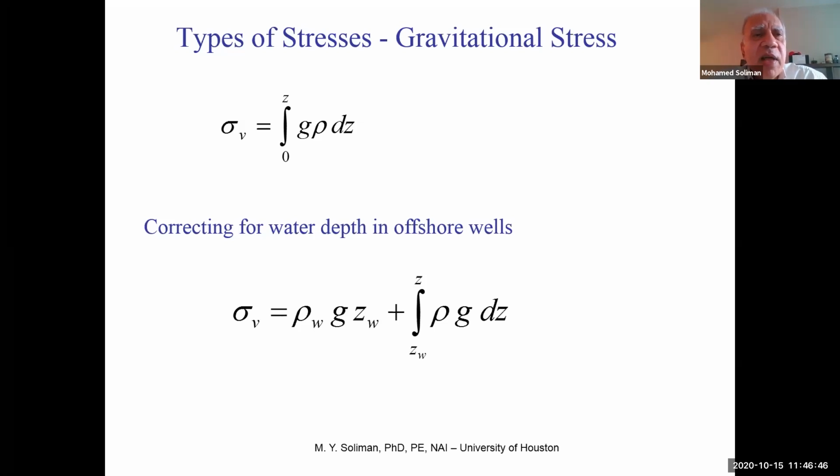So 2.65 times 0.433 is about 1.1 psi per foot. But if I give you more information, you need to do it correctly, and you can do it easily. That's exactly what logs do when they calculate stress for you. All they are doing is calculating the vertical stress. We'll talk in a minute about calculating the horizontal stress.